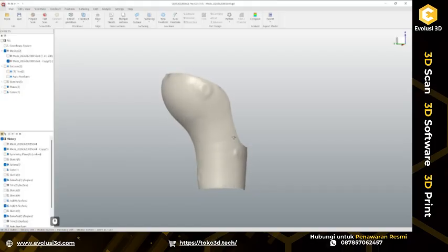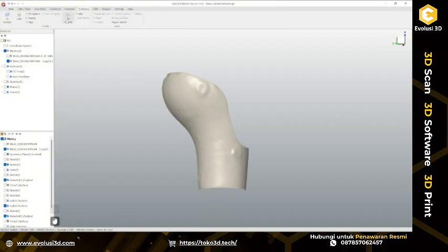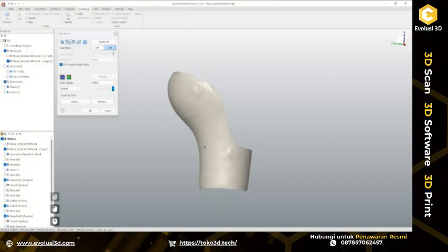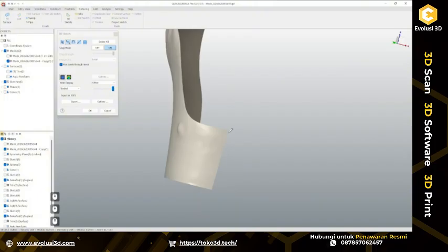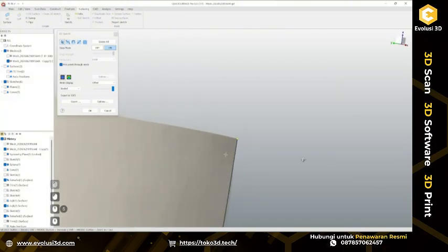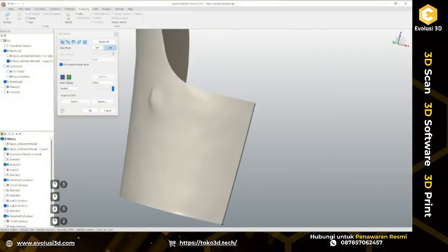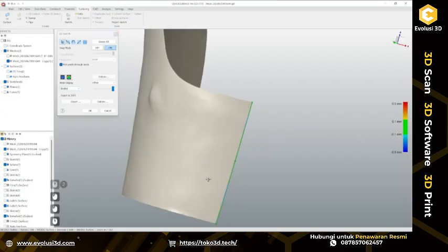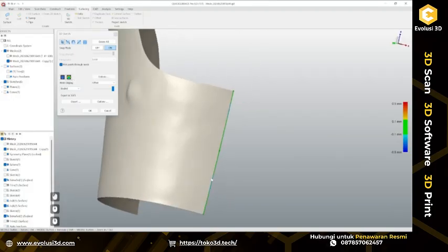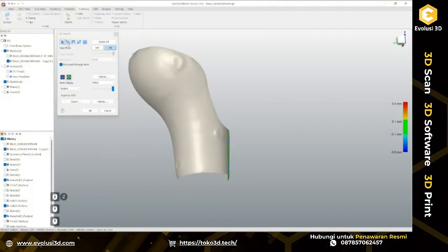So now, the first approach would be to come over to the Surfacing tab and use 3D sketches to define boundaries of this surface. So let's go. I will use just like 2 control points here, most likely. Let's snap them directly to corners. Okay, this looks good. We can take a look at deviation, and it seems we are pretty close. We have some small bumps here and here, but in general that should work.